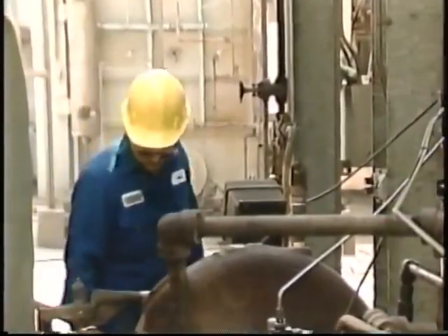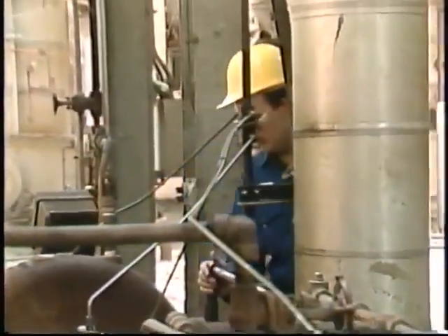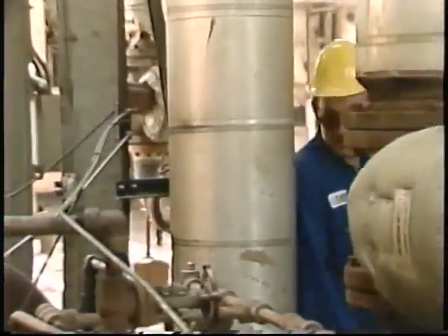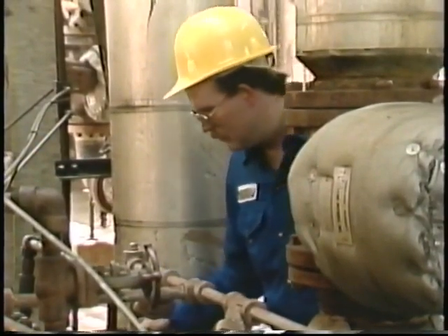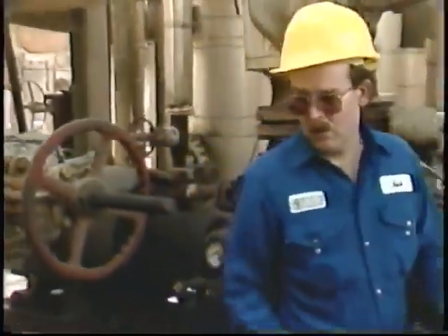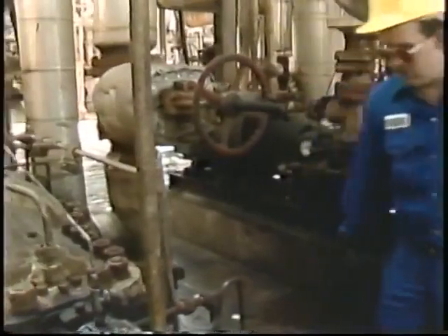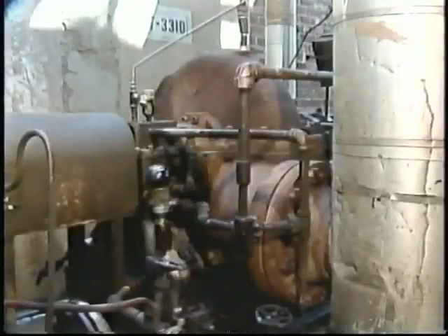During these inspections, you should observe whether the turbine appears to be running smoothly and whether the values of the readings and overall operating conditions are normal for the turbine that you're working with. You should note any unusual noise or circumstance associated with the turbine, its auxiliaries, or the driven equipment. Checking out possible problems early is a good way to prevent more serious trouble later.